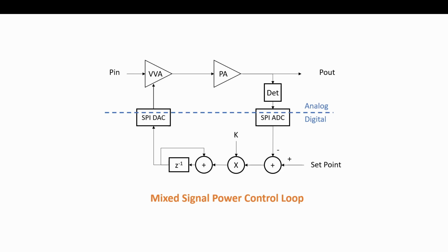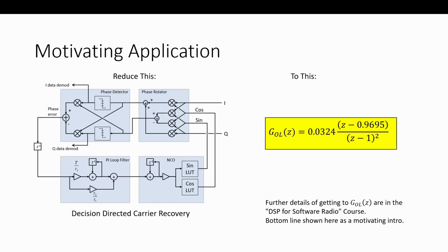And all this stuff in here, you're going to see more later. That's our loop filter, our magic loop filter that's going to float this digital value to what it needs to be, DAC, converting it to analog so that we have zero error. So it's setting the output power based on, in this case, a mixed signal design.